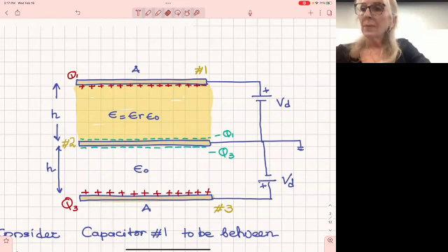And now these conductors see each other. That is called crosstalk. They're tied to each other through the charges. And what is going to happen? You're going to have one capacitance here and one capacitance there. And if this conductor was extended even further, but this was terminated, it would have a third capacitance between the upper one and the lower one. So you have all of these capacitances, which we call parasitic capacitances, all right, and crosstalk between the conductors.